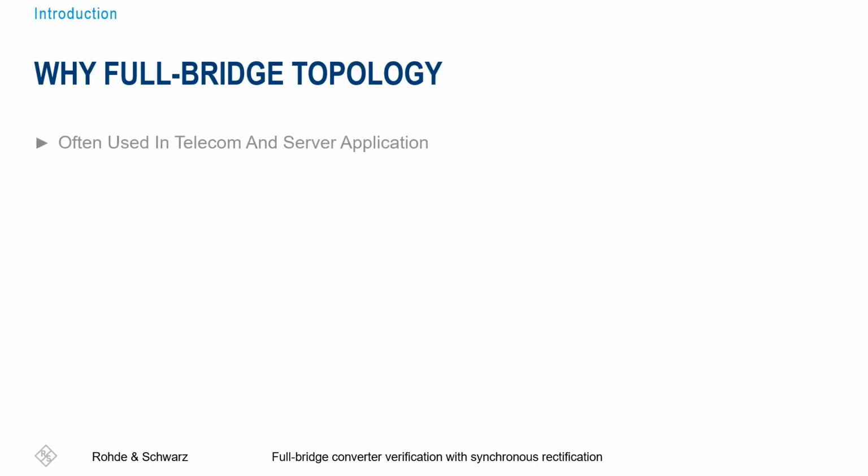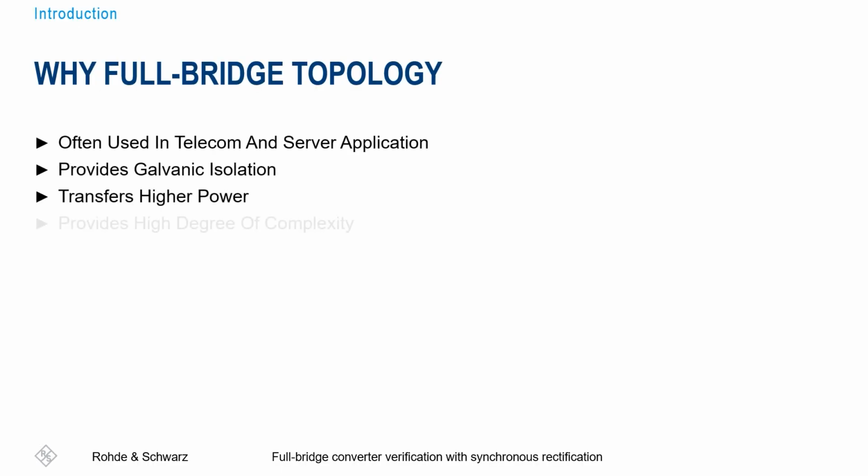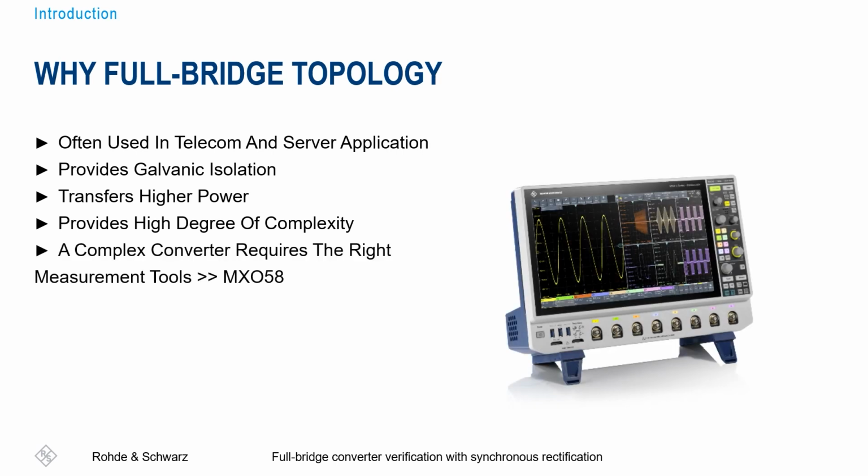So the big question is, why did I choose the full bridge converter design for today's presentation? Well, it's very often and frequently used in telecom and server applications, so really a common topology. It provides galvanic isolation, and that is exactly the topic I wanted to cover today. It also transfers higher power, and it provides also a high degree of complexity. And therefore, of course, we need also the right measurement tools to have the capability to solve this complexity, or simplify it, basically.